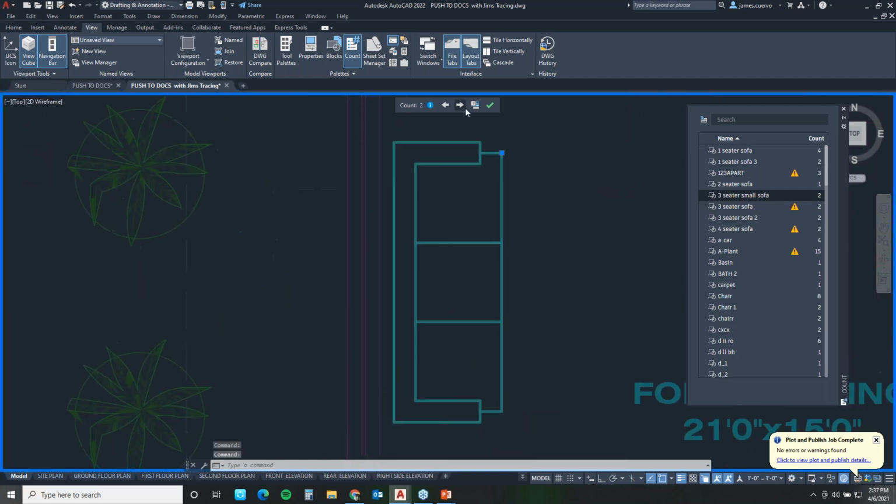We know that, right? But now when I hit this, it's going to take the number and allow me to place it. Now, the way to actually use this is if you have an existing table, rather than insert field into a table, you can go ahead and directly input the field this way without having to go through that other dialog box for tables. This is a little shorter, and you can place it where you want.